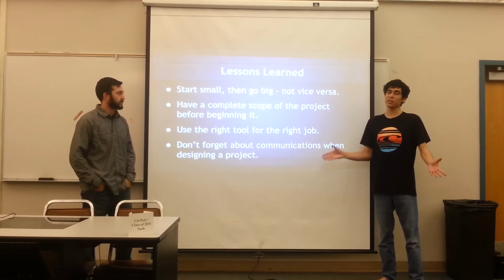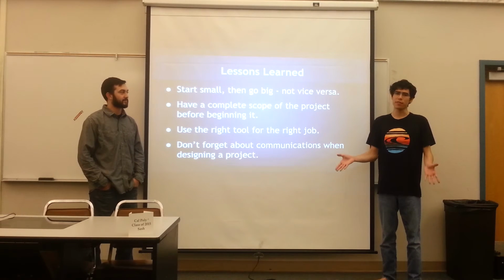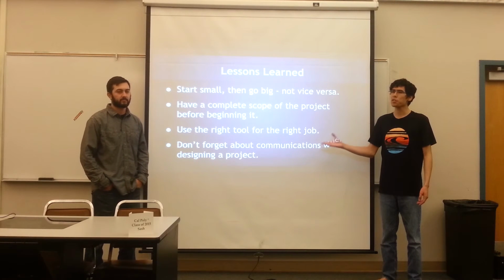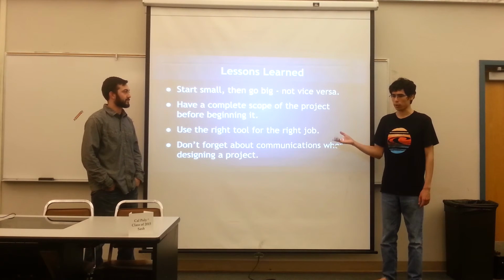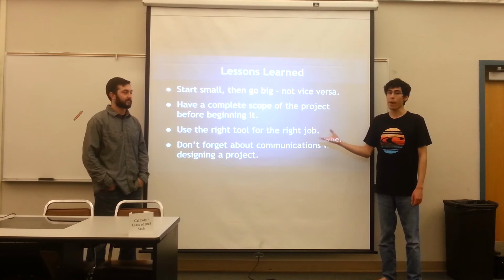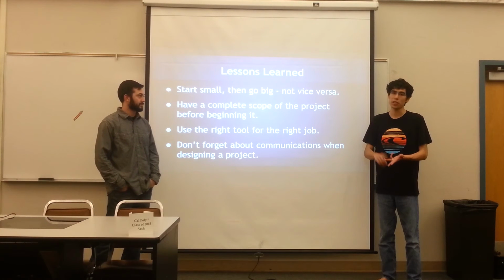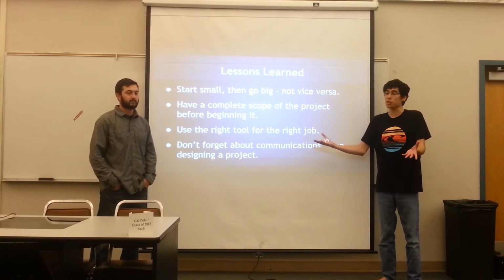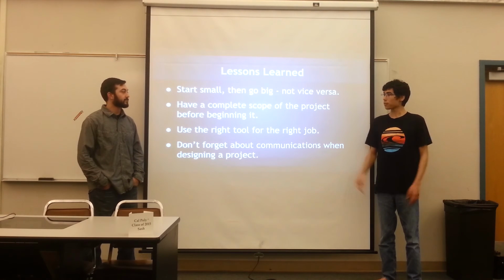Our third lesson is to use the right tool for the job. While the MSPs are very useful, they are 16-bit, mostly integer math devices. Meanwhile, in our project, we're doing a lot of digital signal processing. We could have been much better served with, for example, an MSP 432, which uses a Cortex core, which is a 32-bit core with a built-in floating point unit. That would have made a lot of our math a lot easier because it would have had built-in support for multiplication and additions and lookups. Would have made a lot of our tables a lot smaller and a lot of our math a lot easier. In addition, we could have cut down on most of our cores and a lot of our components because it just has more pins.